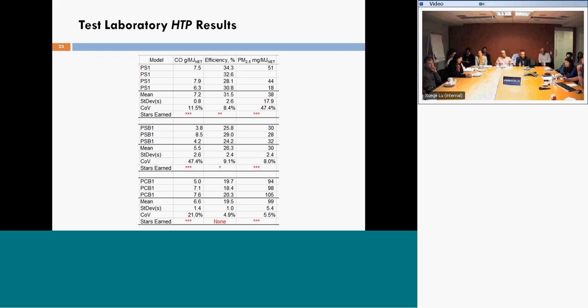So every time you go to cut a branch from a tree, we weigh that branch. If you were to do it 20 times in a row and recycle your fuel forward, as people actually do, you take the energy that's required from the forest, and that goes in the bottom of the equation. The National Standards Committee preferred the term overall thermal efficiency. I've used the term system efficiency, but it relates directly to fuel consumption. Efficiency is a measure of something happening inside the stove. It does not report fuel consumption. So you have to be careful when someone says, my stove is X efficient. Which number did you put over which one?